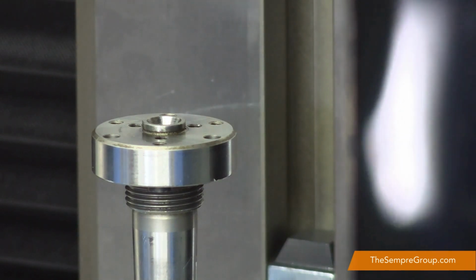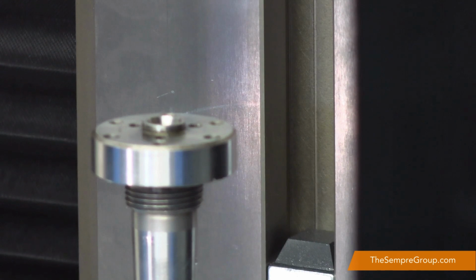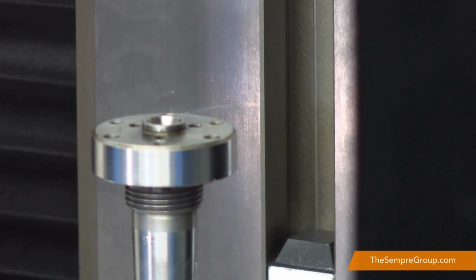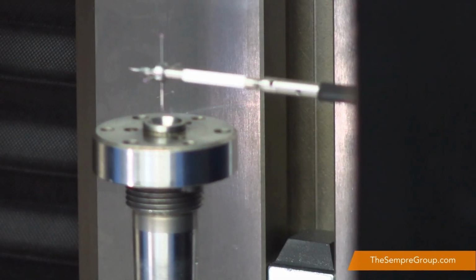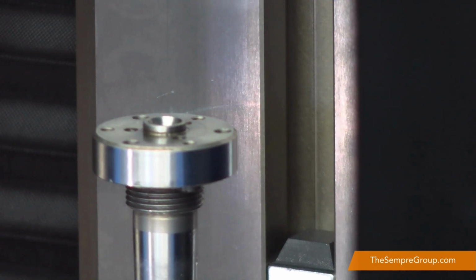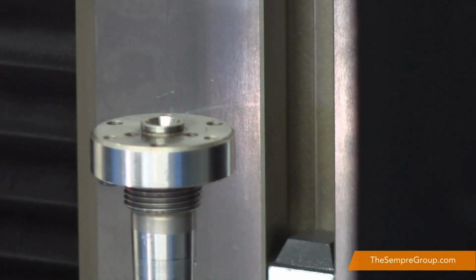we've got a change rack, so we can house up to 3 probes, or 3 different types of probes. So we're swapping over to our star stylus now, and we're going to use the Z negative tool to measure the internal angle or chamfer. So that's now coming in, and we can see it's going on the inside of the component, and it's measuring the profile.